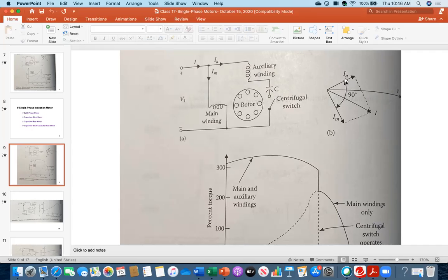So that is causing the leading power factor. IM is as it is. IM is always lagging. Now you see the angle is much higher, it looks like almost 90 degrees. Because in the torque equation T = K IM IA sin alpha, if you can make alpha 90 degrees, that is the best situation. That will provide you the best, maximum torque.